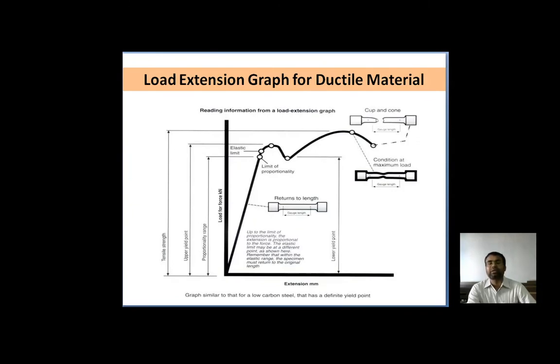The plastic deformation does not mean that the deformed material is a plastic or a polymeric material. The bending of a wire, such as a paper clip, is illustrated in the figure. So the wire is bent a little bit. It will snap back when released. That is showing the movement. With a larger bend, it will be unbent elastically to some extent on release, but there will be a permanent bend because of the plastic deformation.